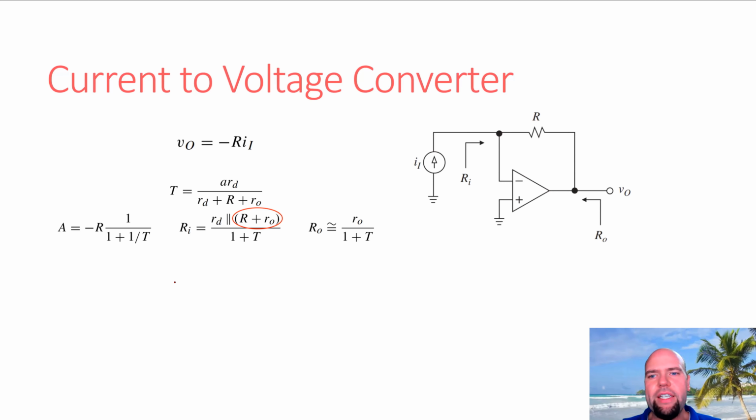So here you've already basically seen this, but this is the basic current to voltage converter. Fairly straightforward. We talked about this, right? What topology is this? This is the shunt topology. So again, we're sampling the output voltage, which is in shunt, and we are combining currents in shunt. So it's the shunt topology. We've spent a lot of time talking about this.